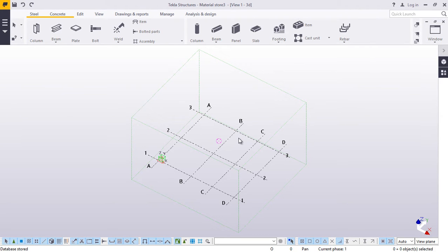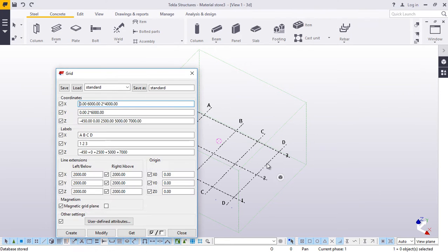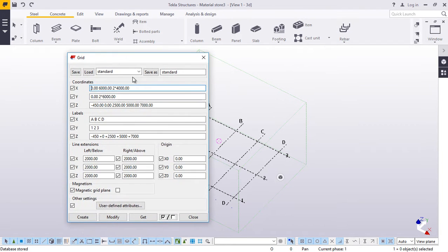Welcome to this presentation. Today I'm going to model a portal frame with a ventilated roof and a louvered side clad kind of a structure. Let's kick off here by going straight to modification of grid. We'll use this default grid for modification by feeding our own dimensions on these grid properties. We'll do away with all this and type our own dimensions here.